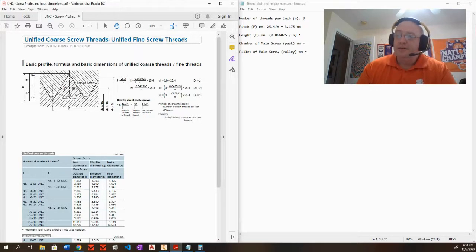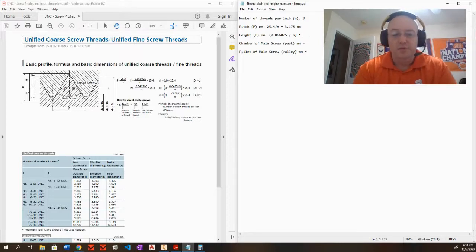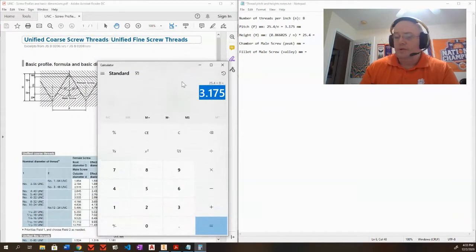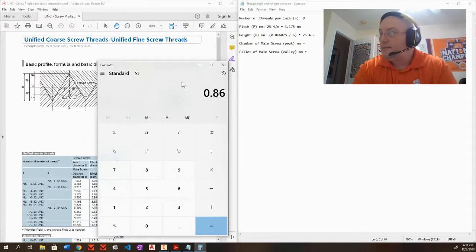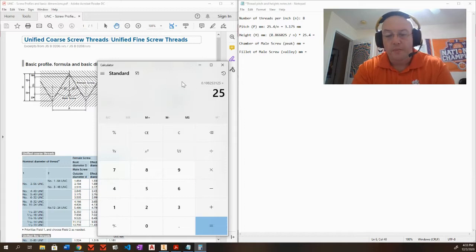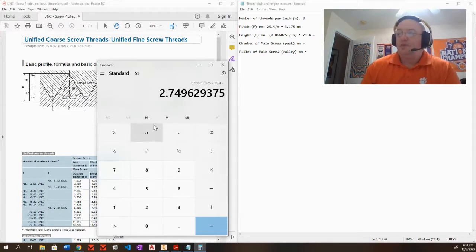So to get that, we have height is 0.866025 divided by n times 25.4. Okay, so let's go ahead and pull our calculator back up again. And we're going to go with 0.866025 divided by 8. That's our number of threads. And all of that multiplied by 25.4. This gives us 2.749629375. This is our height in millimeters.